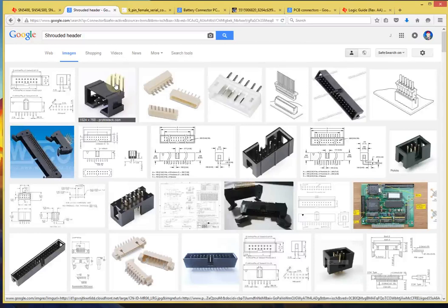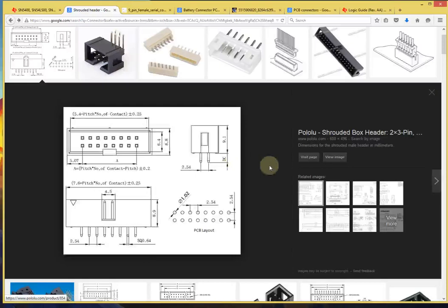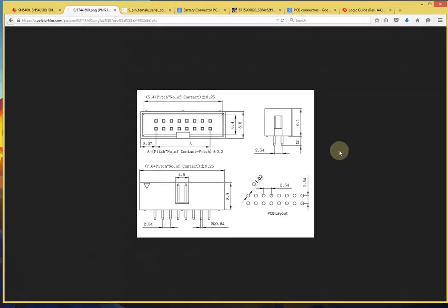Of course, when you're starting out, you want to start out with the most common tools or most common components, and my recommendation to you is to look at hobbyist type of vendors such as SparkFun or Adafruit, which provide some very common parts, and start with common off-the-shelf parts. But regardless of the part that you use, you need to be aware of the footprint, which comes from the mechanical drawing, right? Let's take a view at this particular header here.